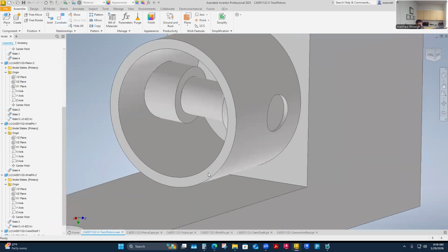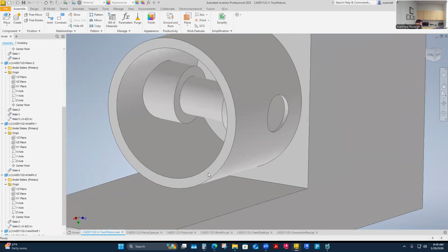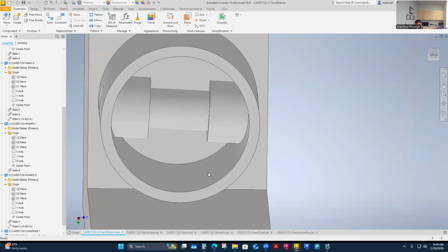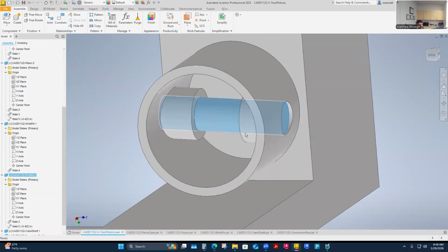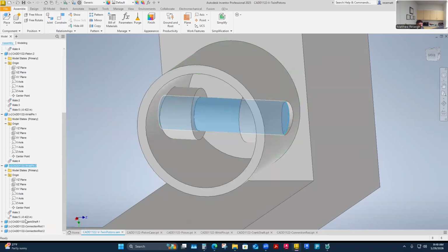And so plane to plane is way easier if it can be, but a measurement you can figure out. Like I was able to figure out a measurement to place this pin centered in there. And mine is a negative 0.4215. But it took me measuring the pin length, measuring the opening length, and figuring out the halves of each and then adding them together or subtracting them from each other. And then I came up with a dimension.